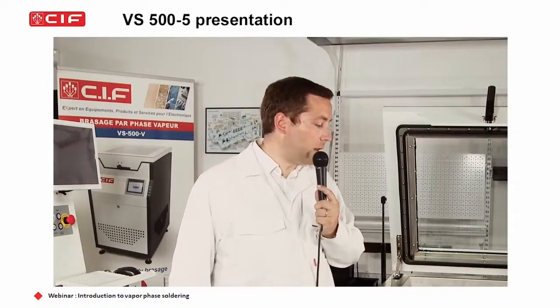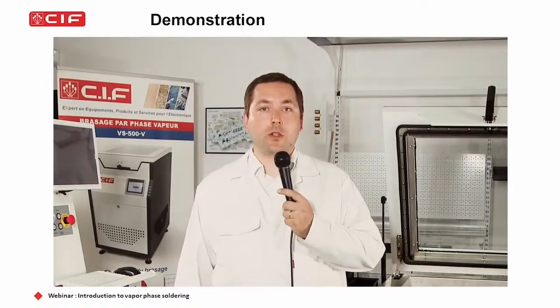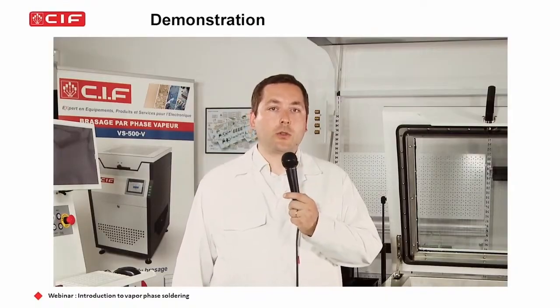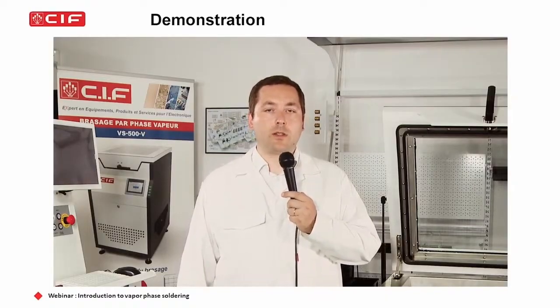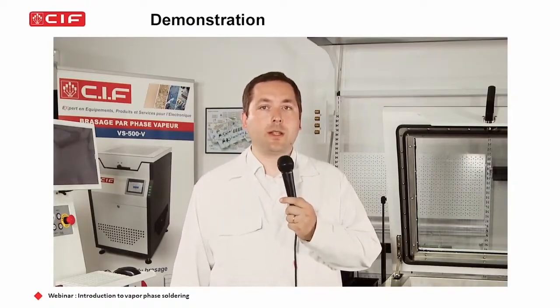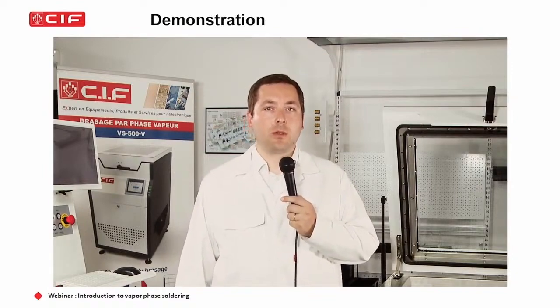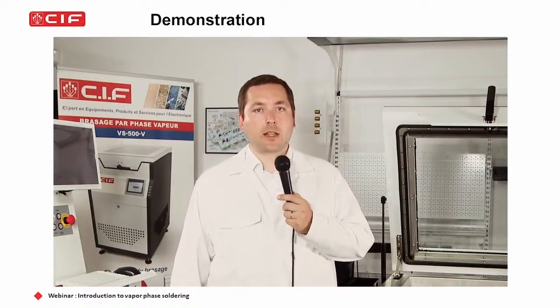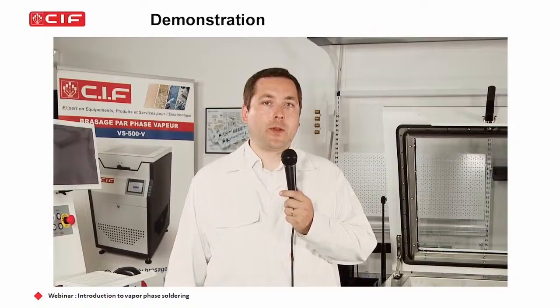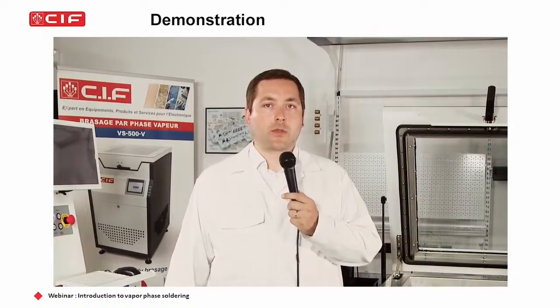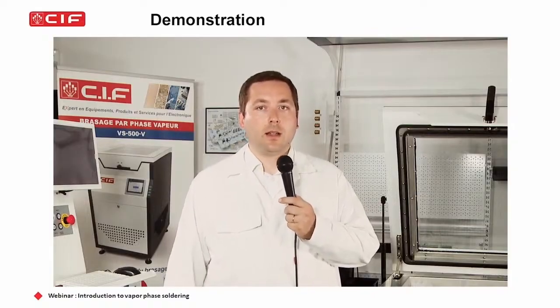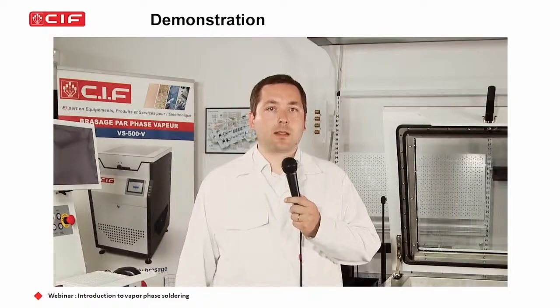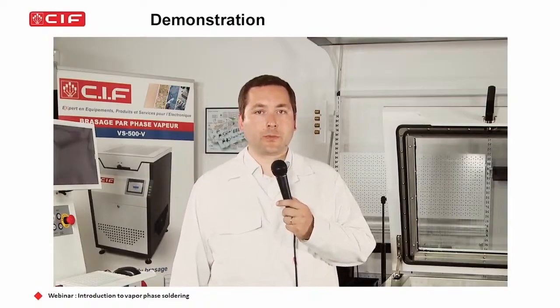So let's now jump to the demonstration. In order to keep our webinar within a reasonable time frame, we have already heated up the system to idle. It takes approximately 12 to 15 minutes to get from room temperature to idling, and it mainly depends on the Galden type used.